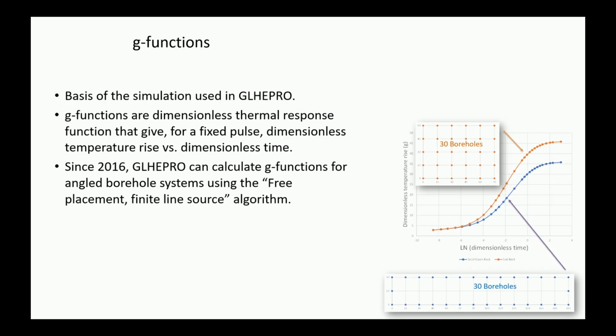So the basis of the simulations is called the G function, and this is a thermal response function that gives, for a fixed pulse, the dimensionless temperature rise versus dimensionless time. And maybe almost all of the complicated mathematics are in getting this G function.